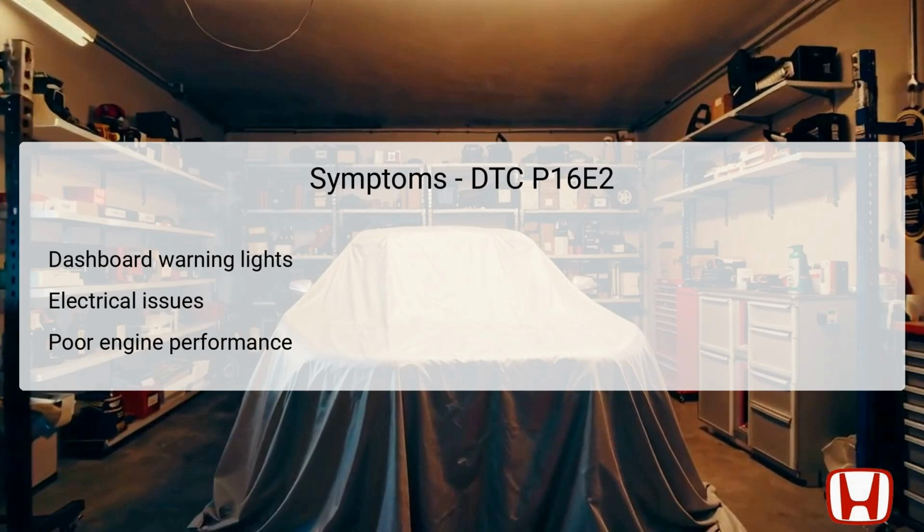Understanding the symptoms associated with DTC P16E2 is vital for diagnosing the issue effectively. Drivers may notice dashboard warning lights illuminating, often indicating electrical problems, as the PCM struggles to manage power distribution without reliable signals from the alternator. Additional symptoms might include a discernible decrease in engine performance, as the vehicle's electric systems could malfunction due to insufficient power. In some cases, vehicles may experience electrical failures, such as flickering lights or unresponsive electrical components.